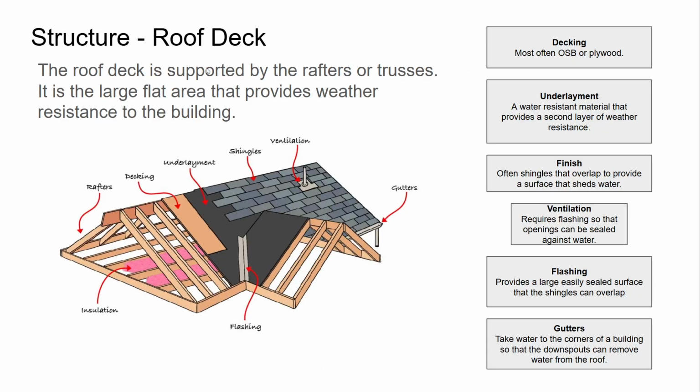So finally, there's the roof deck. So what is this again? It's a joist. This one happens to have a whole bunch of members going this way, kind of odd, but it happens, and there should be some joists going back the other way. Insulation runs in there, rafters run in there, the ridge boards. And once you've got that, the decking goes onto the rafters or the battens, and that's just OSB, oriented strand board, or plywood.